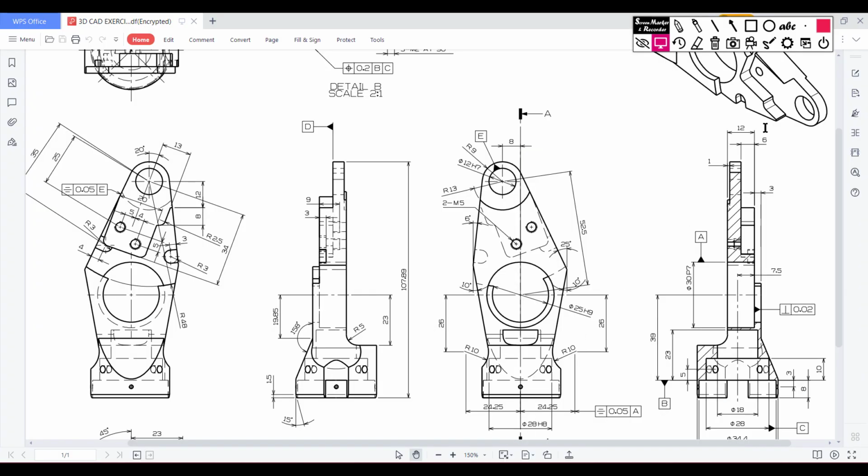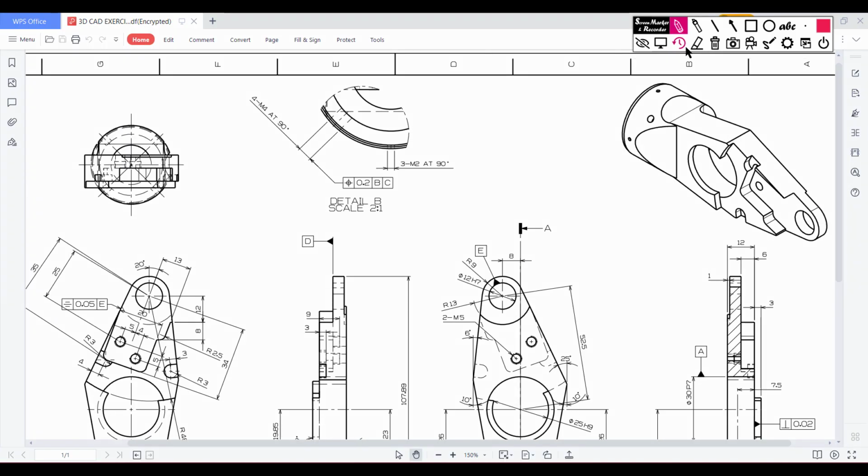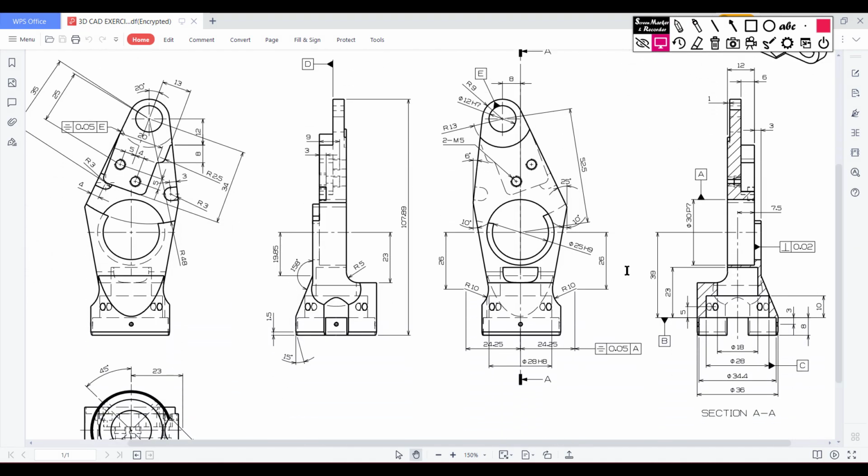Now going to our sketch. Now in our sketch, this time I will cut this portion, this back portion. And how are we going to do this? So in our sketch we can see that from this center line, we have a distance of 23 unit here. Then I'll draw a line, and then I will fillet it to R5 unit.